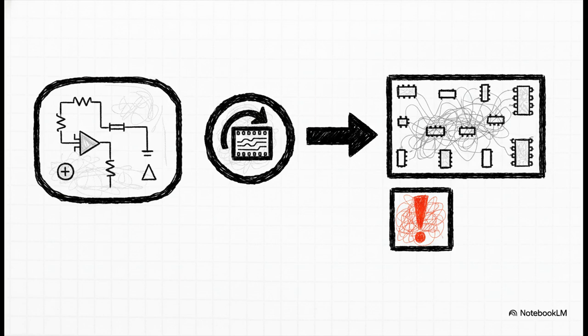The very first thing you're going to do in the PCB editor is hit that Update PCB from Schematic button. This is the moment where KiCad pulls in all your components and their footprints. You'll also see all these thin white lines crisscrossing everywhere. We call those rat's nests. And yeah, it looks like a mess, but don't panic. Those lines are actually your guide, showing you every single connection you still need to make. Just be sure to watch that output window for any errors. If you see one, you've got to go back to the schematic and fix it first.